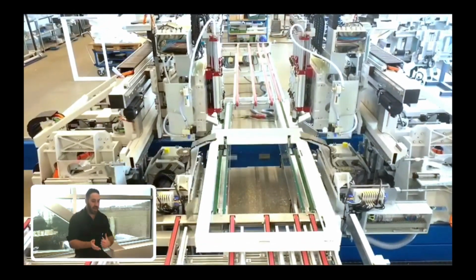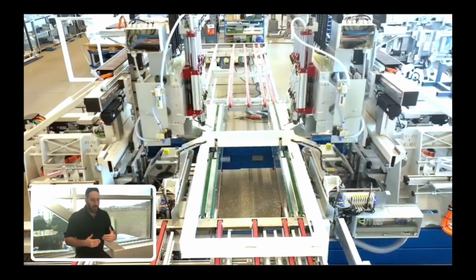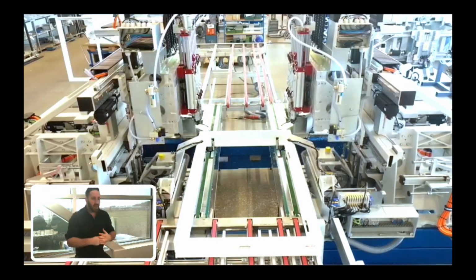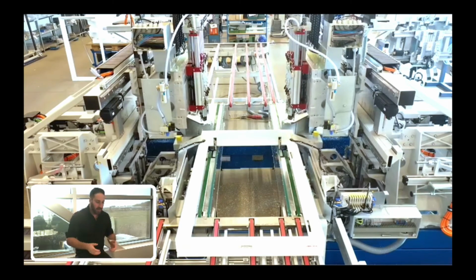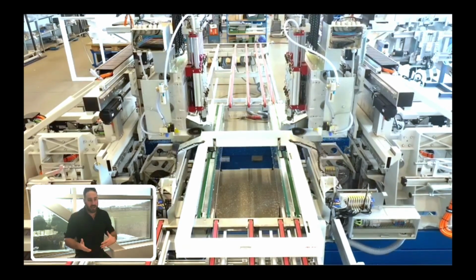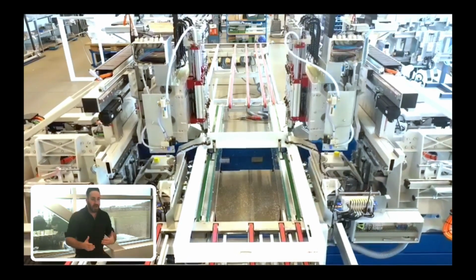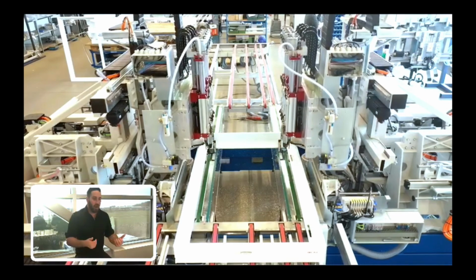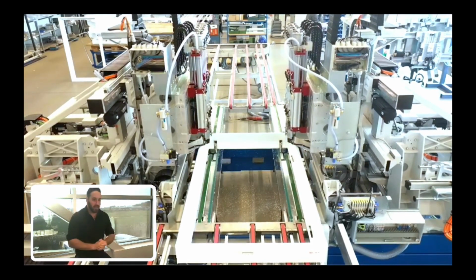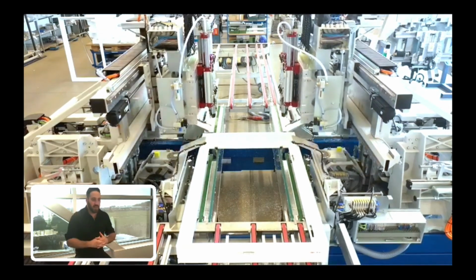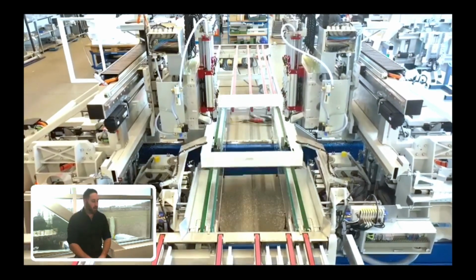So if I'm taking, again, my example of a 1000 by 1000 square, and for any good reason your welder is off, the part goes into your corner cleaner and it should be 1000, but it's 999. Well, the corner cleaner is going to adjust itself to the right measurements and start its cleaning. So you're not going to have a clean that's off the corner, instead of only giving the information to the machine that it would be a 1000 square. So those are things to, again, keep in mind.